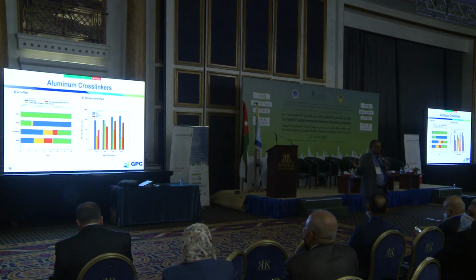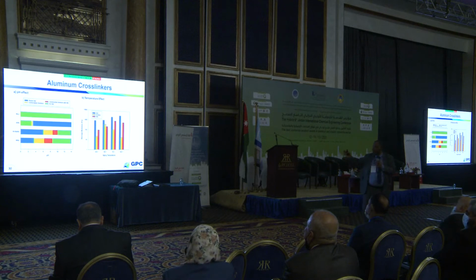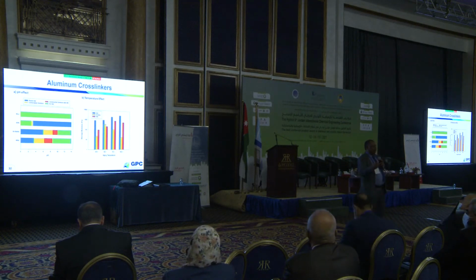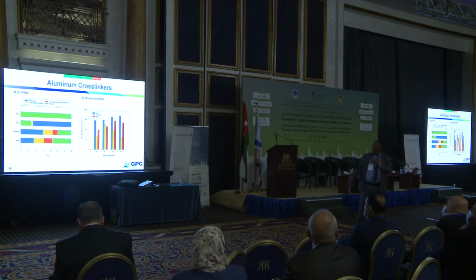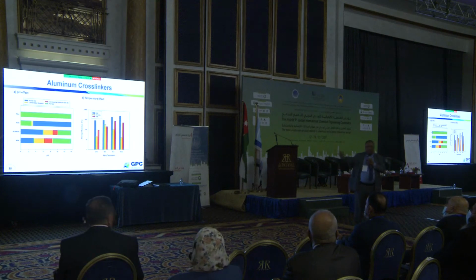Later on, an important contribution that we made is that we work a lot on cross-linkers, especially inorganic cross-linkers. We developed the cross-linker aluminum acetate. We studied different types of aluminum. We moved from chromium to aluminum because it's more environmentally friendly, especially if you want to use it for offshore. And we found aluminum acetate is the best. You can play with pH and get different strength.